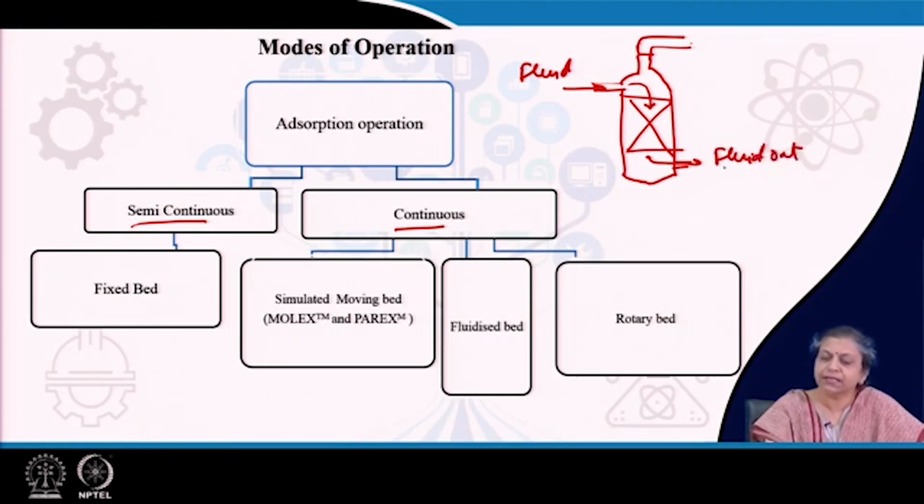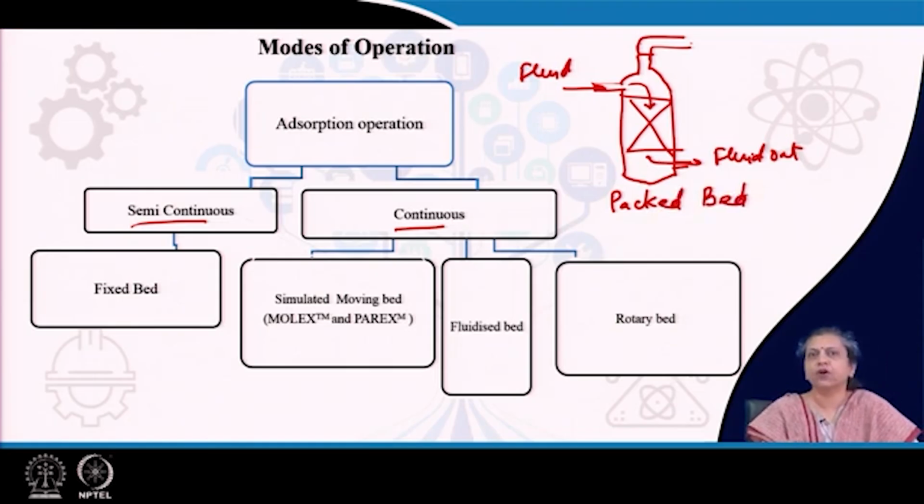So, in this case, since it is only the fluid moving, the solid is in the form of a packed bed, it is stationary. Therefore, this is known as a semi-continuous mode of operation, although the contact is continuous contact, it is a semi-continuous mode of operation. These generally take place in packed beds, and are known as packed bed adsorption.